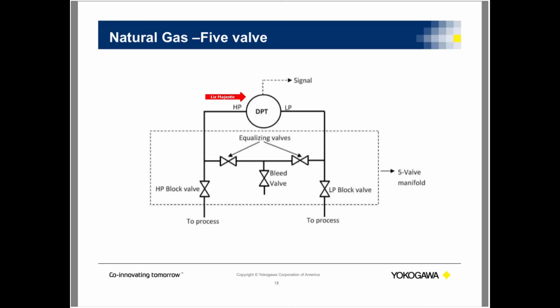You're going to hold this open until you can't hear the gas flow anymore, and the result should be the valve should be completely open. So your downstream will be fully open after that. You're going to observe the zero on the transmitter and adjust if necessary.